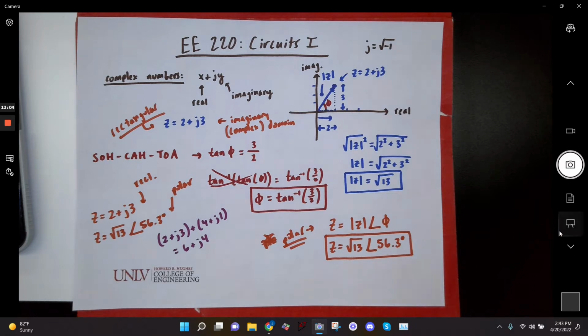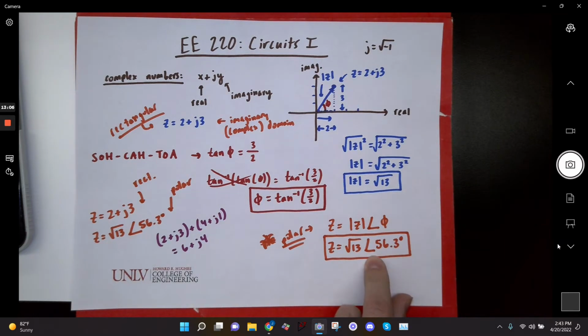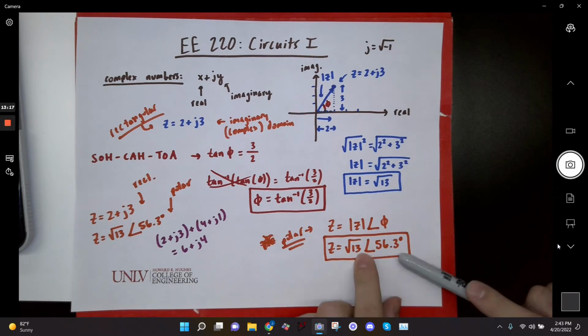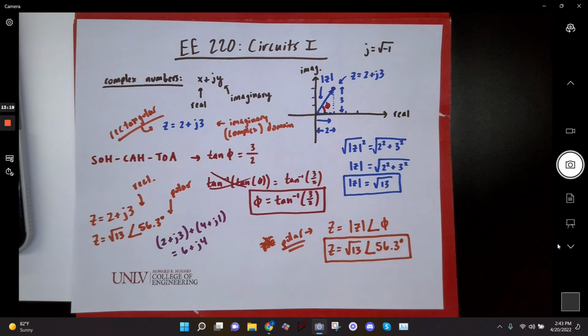It's easier to look at this when you start getting used to these phasors than it is to look at 6 cosine of 2 pi times 1k times t minus 15 degrees. That's kind of just overkill. We don't need to know all that. All we need to know are these two things in most cases. Because when we're working on a system, we're going to know the frequency. We don't need to see it in all of our equations and keep writing it.